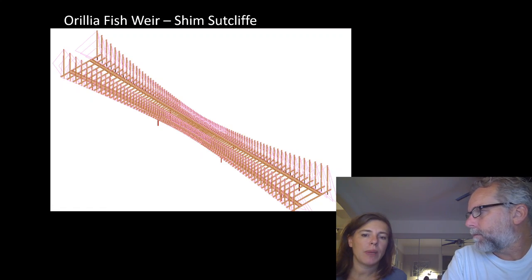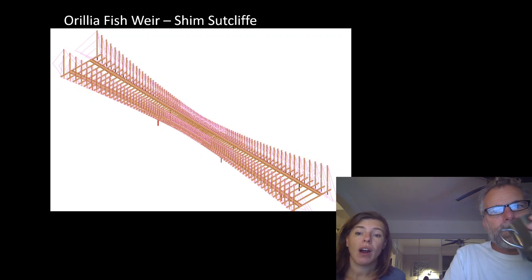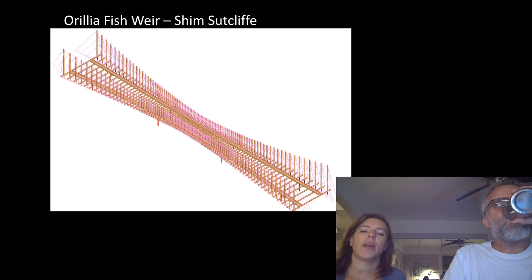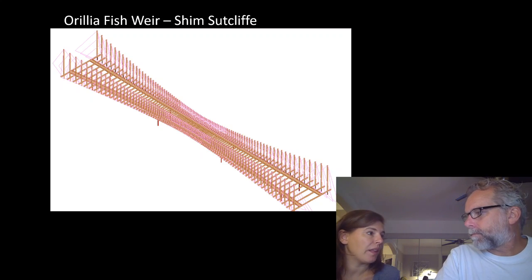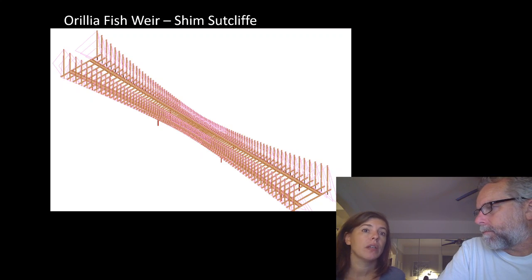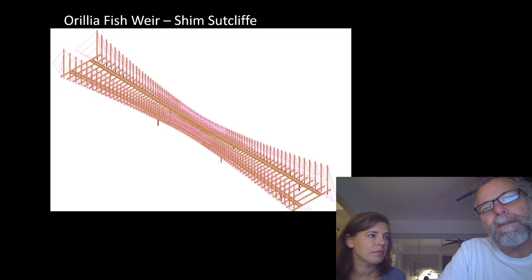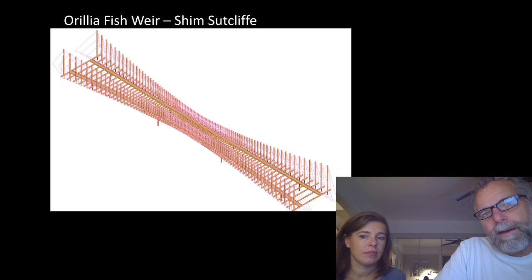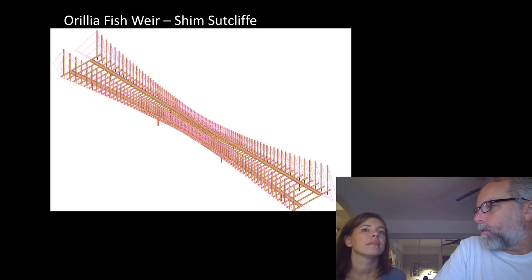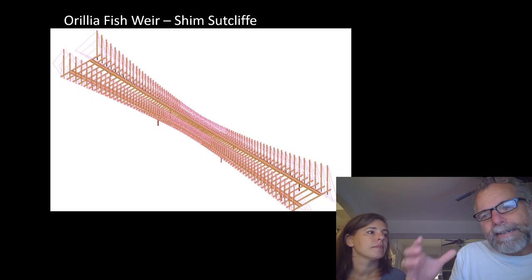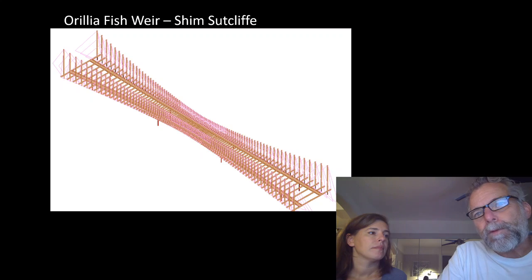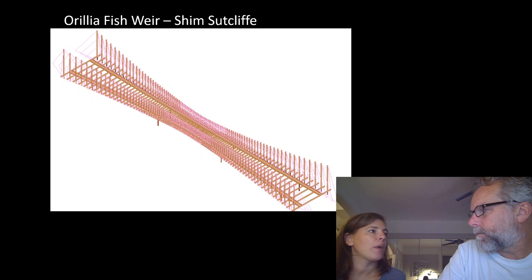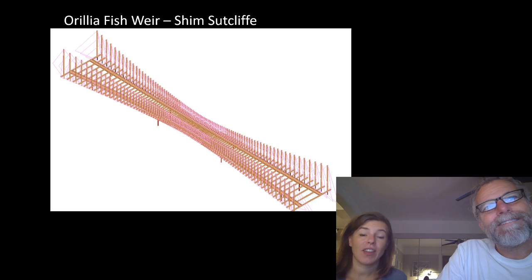And the reason that works is because the load conditions during construction aren't the full use loads. They don't worry about vibration. They don't worry about serviceability during that stage. So the criteria are much lower, which is why you can use just those chords temporarily for that part of the construction. Yeah, just the live load. We designed for about 25% of the live load in construction. So for the life of the structure, the live load is the densest possible accumulation of people. Whereas during construction, there's a recognition that it will be lightly occupied, and we're generally probably not having a party on it in the middle of construction. Although I've seen that. Yeah.